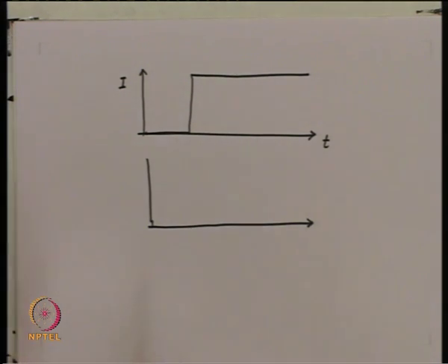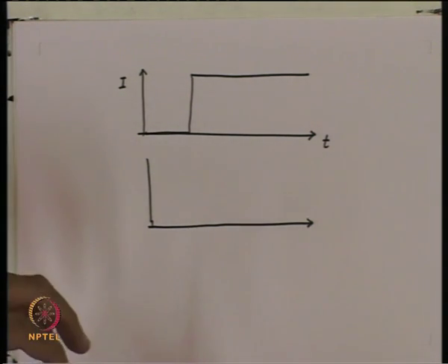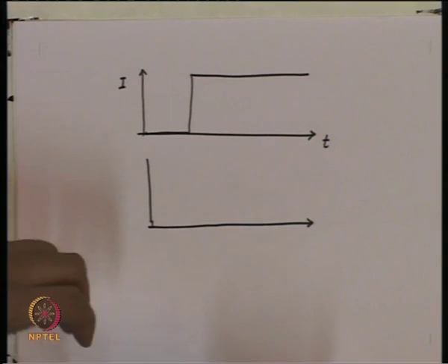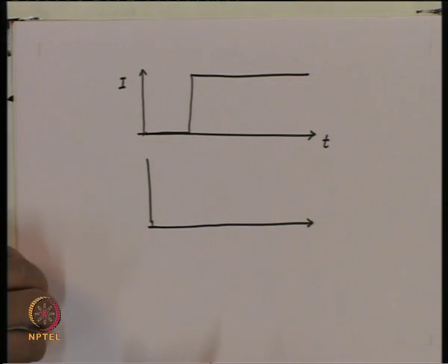So, a large number of electron holes will get recombined, and you will get essentially a pulse of light. But as soon as the stimulated process starts, the depletion region will be depleted of the electron holes. So, the gain of the system will fall and the stimulated output also will reduce.